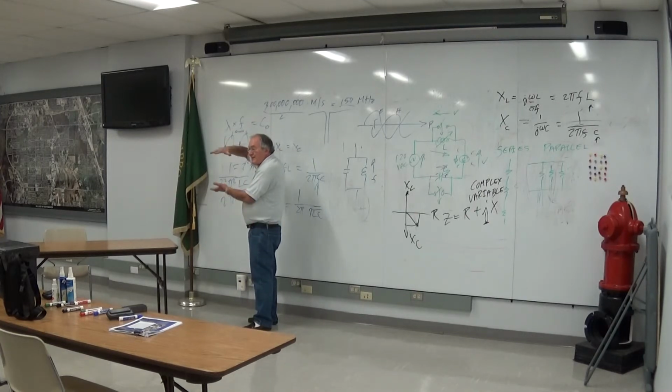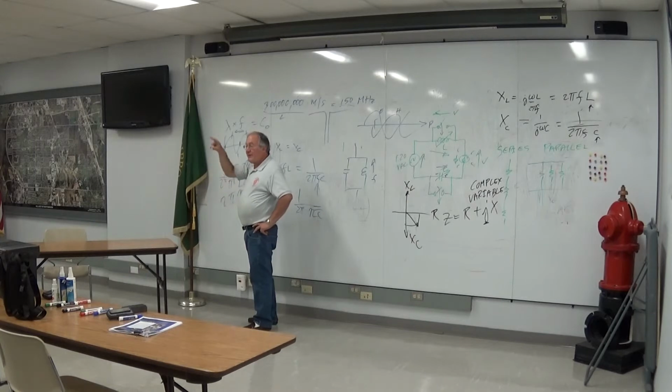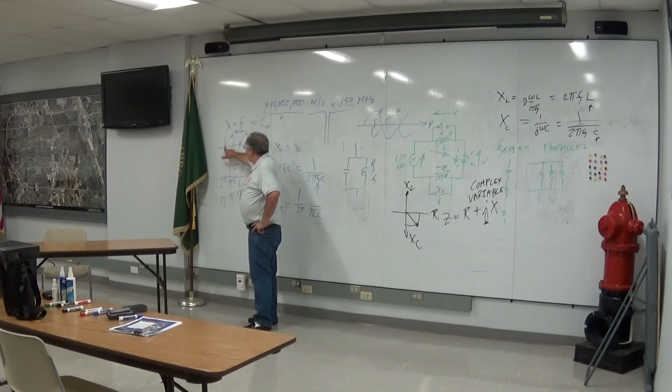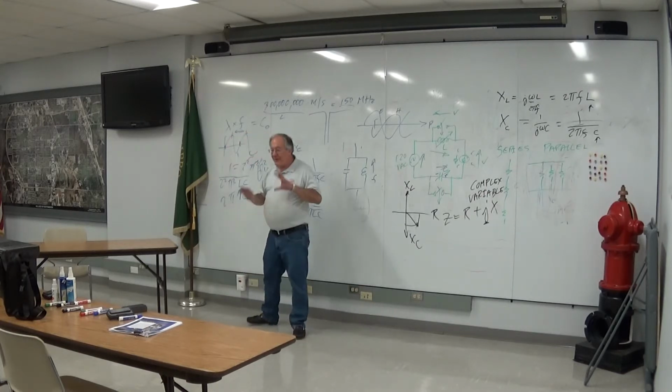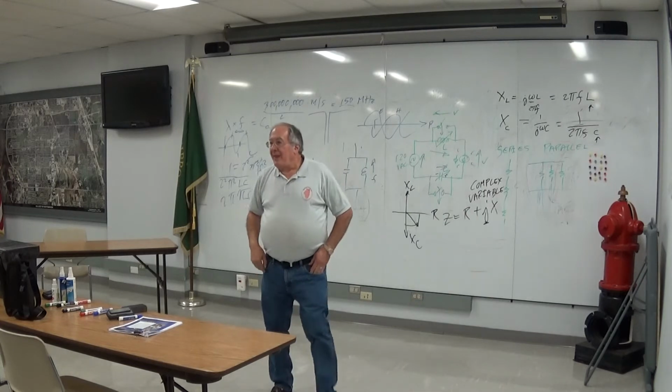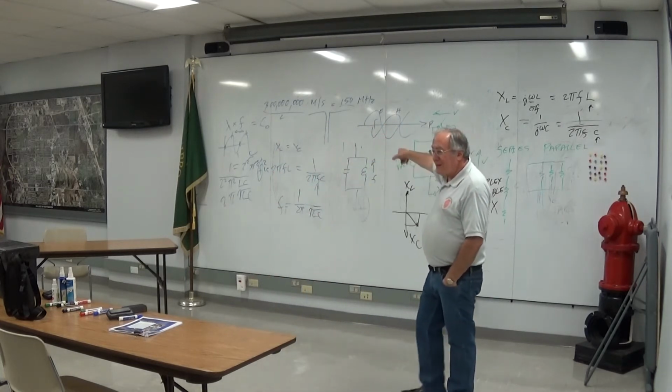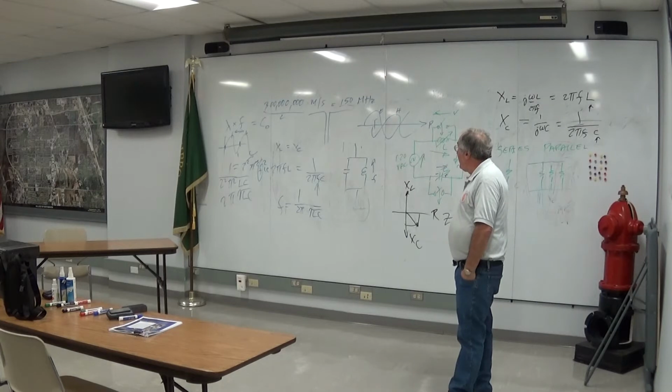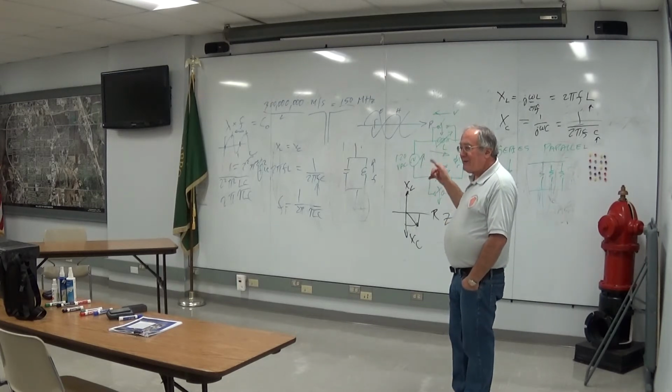Vertical plates in the oscilloscope are deflecting according to the wave's voltage, and the horizontal is being fed with a sawtooth that goes straight line, and then when it gets to the end, drops down and does a straight line build up again. So it goes left to right, and does it again and again, and that's why you get that stationary wave on the oscilloscope. If you have the right sweep rate and the right synchronization, triggering process, we're covering that too. Oscilloscopes will show you what happens over a period of time.